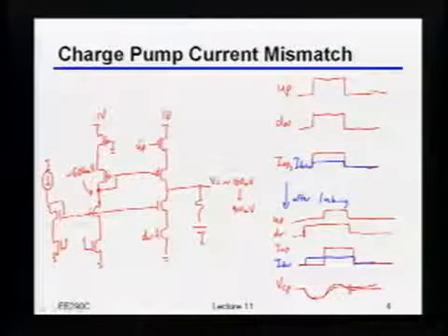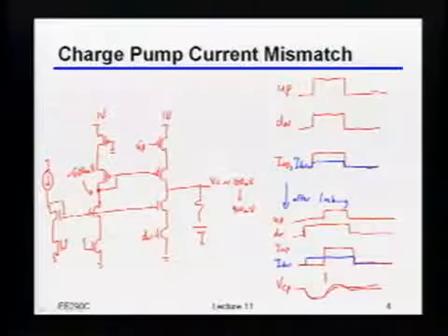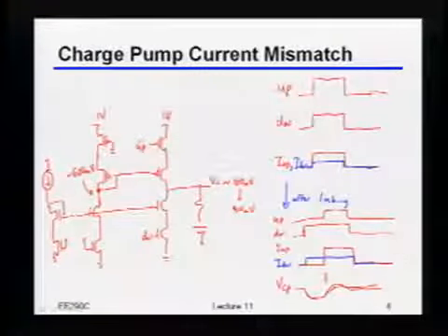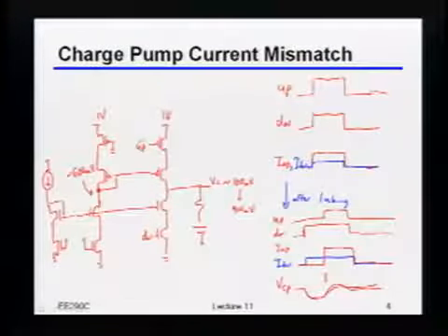But if I keep repeating this every single cycle, I'll see a reference spur, because every n cycles I'll get some cycle that's long and then short. For example, if I do a divide by 10, on the reference cycle I maybe get a short cycle and then 9 long cycles, and then short, 9 long, and so on.